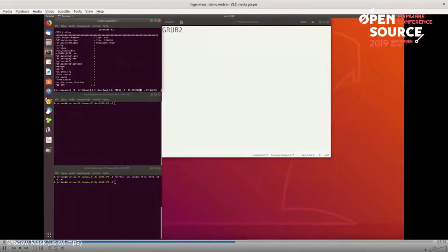Yeah, we can have various payloads use it. We put the Linux kernel in SPI Flash as well as in initramfs, so this machine does not require any additional storage. It's directly from SPI Flash. There is not a lot of space, but still something.